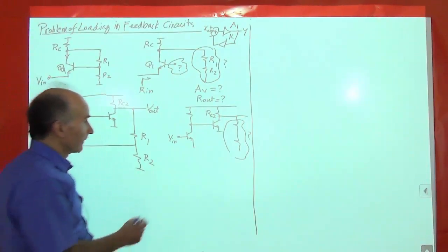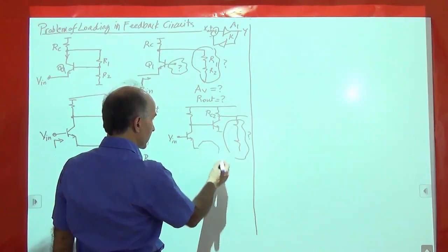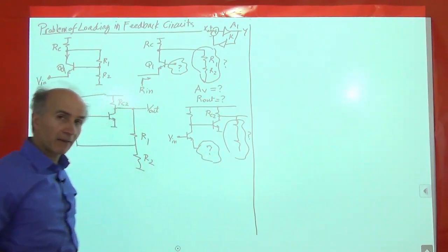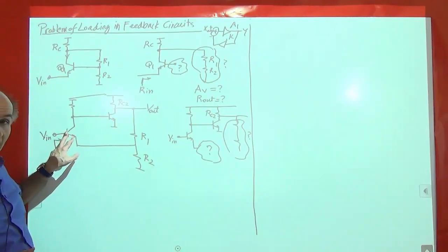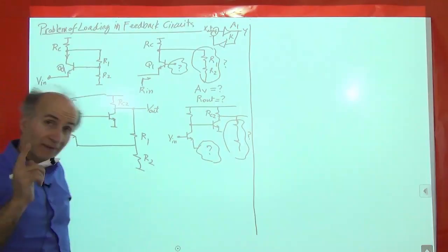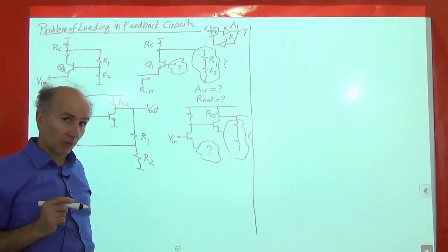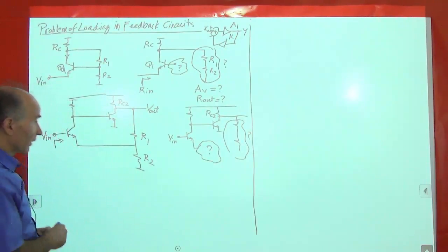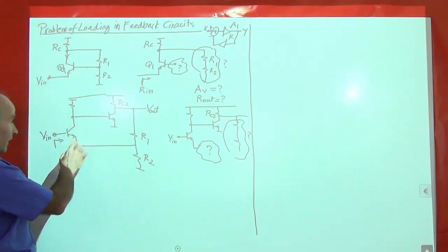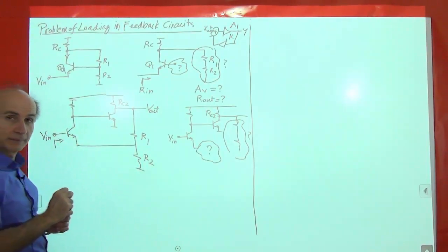Okay, so something has to go here as well, we don't know what, to model the fact that the input transistor is degenerated by the feedback network. That was not the intention of the feedback network, right? The intention of the feedback network was to bring a voltage here. That's all. Because this guy is a voltage subtractor.